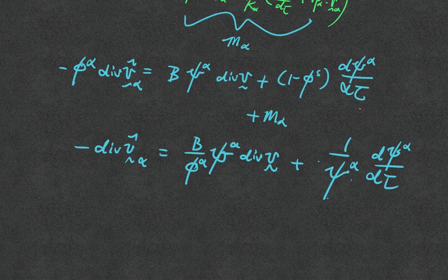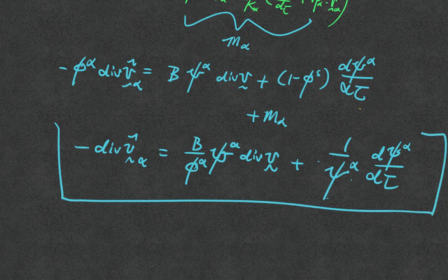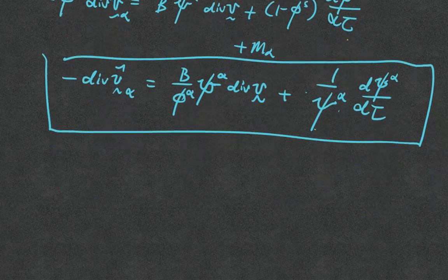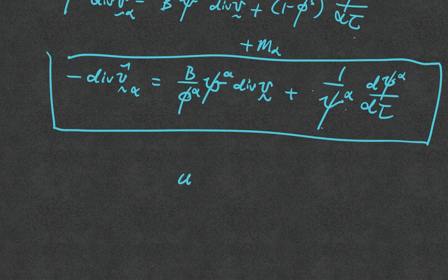So far so good. Okay, this gives us the balance of mass. Now, you will notice that I keep the alpha term there. Why? Because if you think about it, what is the minimum I need to solve? I definitely still need to find the displacement of the solid, and I definitely still need the pressure of the water, right? But now, at the very least, I also need the pressure of air, right? Okay, you see what I mean?